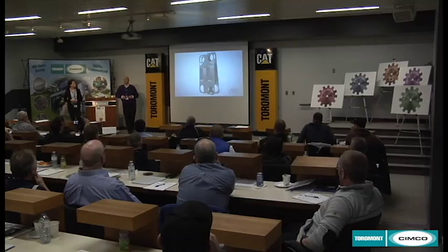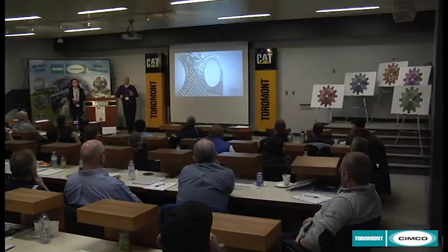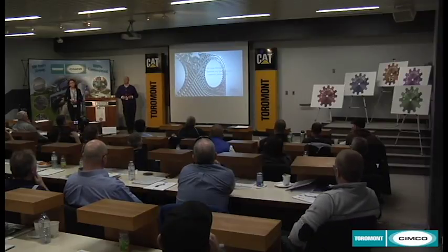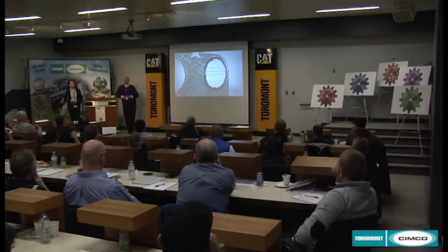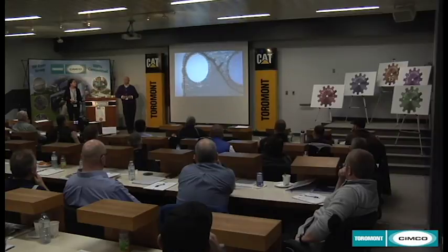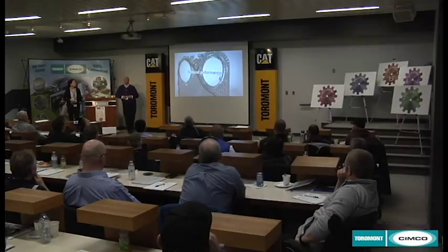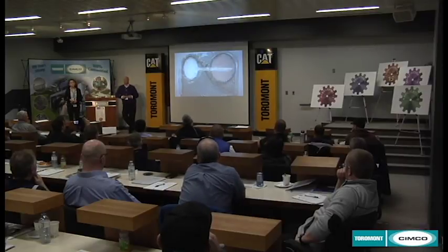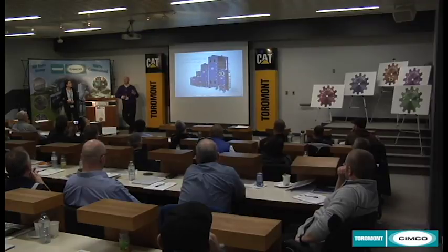plate pack. And then here you see what we do in a semi-welded heat exchanger is take two plates and weld them together to form a cassette. So the refrigerant running on the inside of the cassette, the only gasket that would be seen by the refrigerant would be the ring gasket, which you just saw. The field gasket is on the other side and is typically on the glycol or brine side. We have a separate ring gasket groove, which differentiates us from other manufacturers who actually have the gasket sitting on top of that weld.